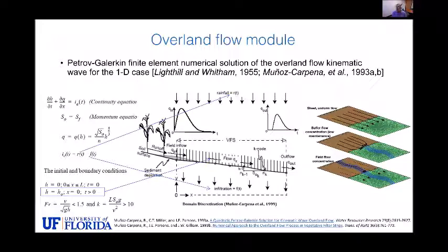You could also have concentration in the buffer, which typically will be the result of low maintenance, aging of the vegetation, ultimately channelization through the buffer. And you could also have an already existing flow concentration in the field that cascades into the buffer, continuing the flow through. Clearly, the reductions expected under concentrated flow conditions will be lower than under sheet flow, and maintenance should be in place precisely to increase the efficiency of these buffers.